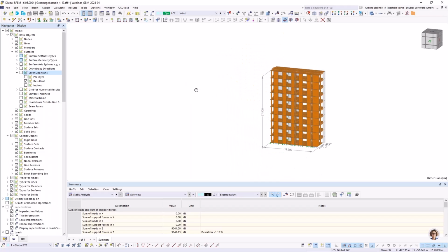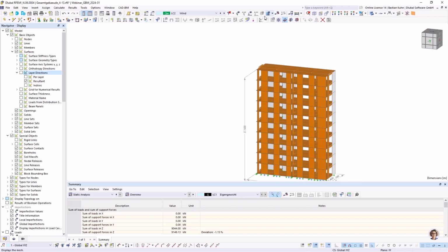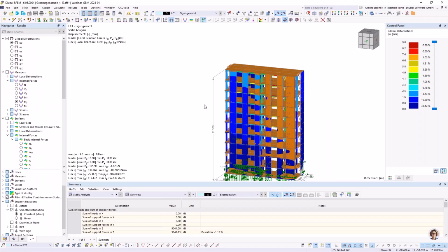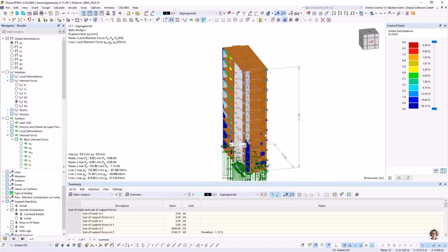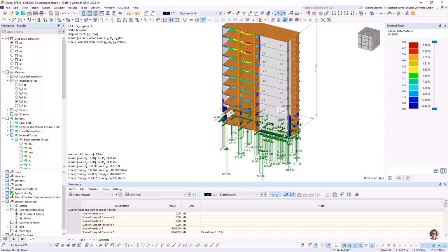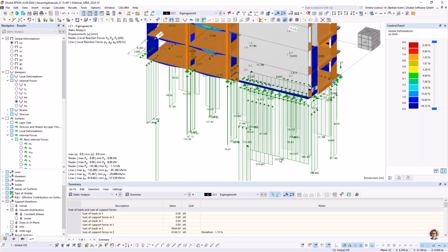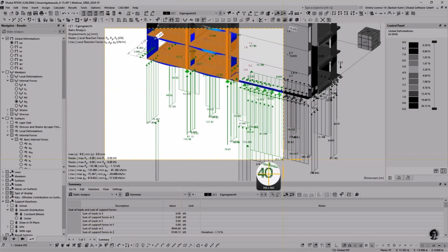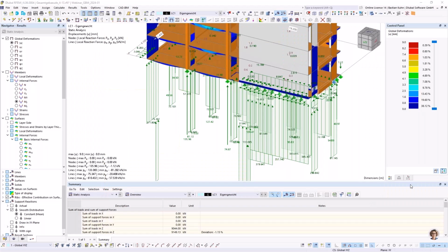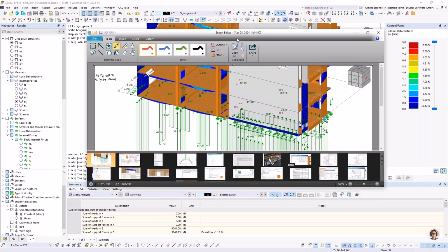Yeah, and in former times, before we did not have the building model add-on or this support reaction tool, customers always tried to calculate it this way. Let's say we have load case 1 with the 2 kilonewton per square meter, and we calculate it, and maybe we can remind just this little vertical force in here, 257. I can put it into my shortcuts also, so just that we remember it afterwards.